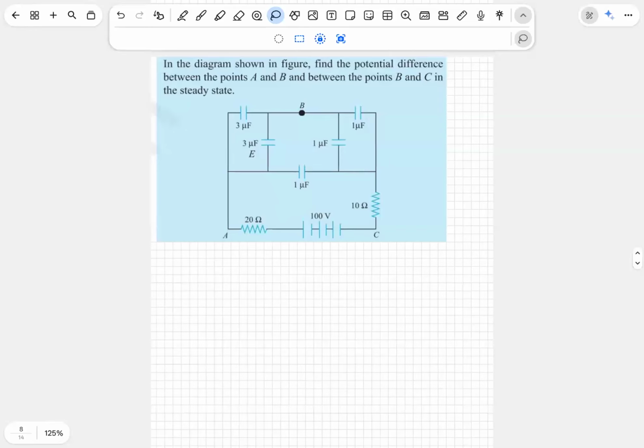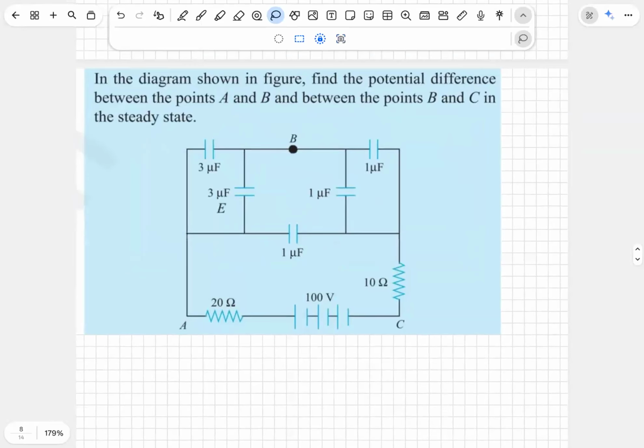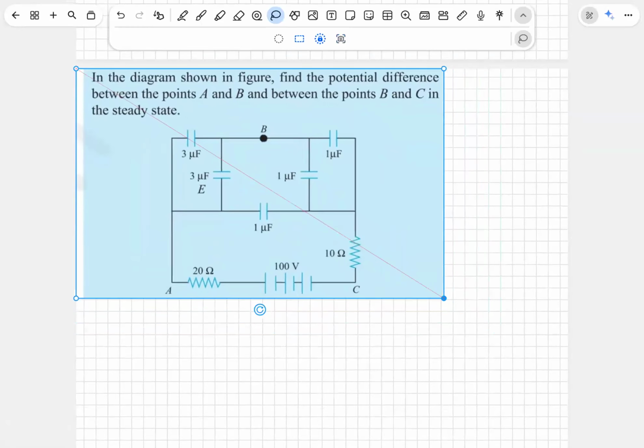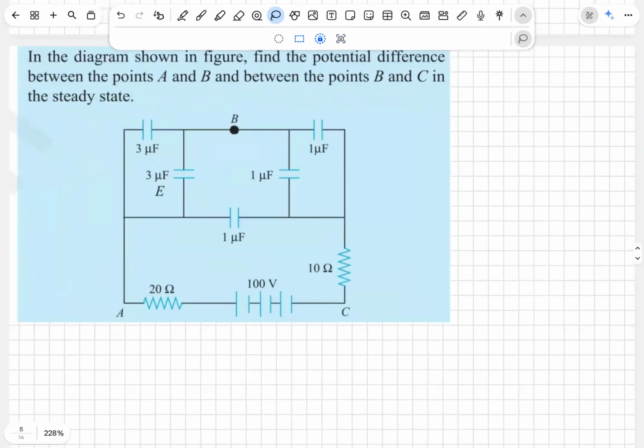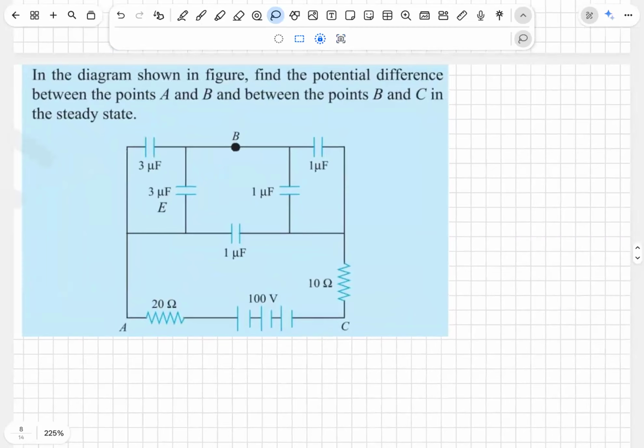In continuation to our previous class, RC circuits, we are working on some simple models. Thumb rules that you need to still remember is, in an RC circuit, at t equal to 0, an uncharged capacitor behaves as a conductor, as simple as a connecting wire. A long time after closing the switch, it behaves as an infinite resistor, an open switch. This is the thumb rule.